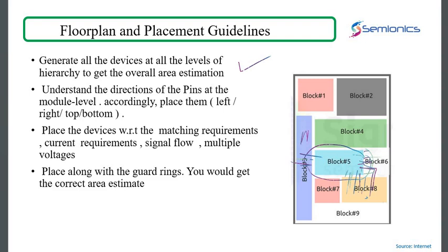You know that this particular module is over here, and these are the signals talking to it. So your pins should be placed over here. The pins which are talking to this module, the pins which are getting inputs from this module, should be placed over here. So likewise, you would get an idea of the pin directions. Every time you don't have to go and ask. You can dig into the top level itself and figure out things for yourself.